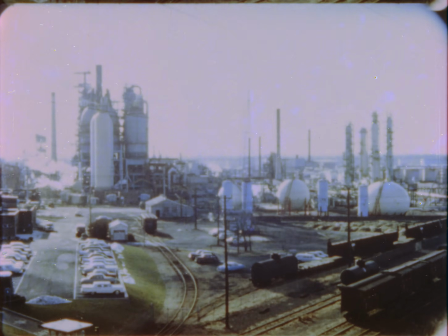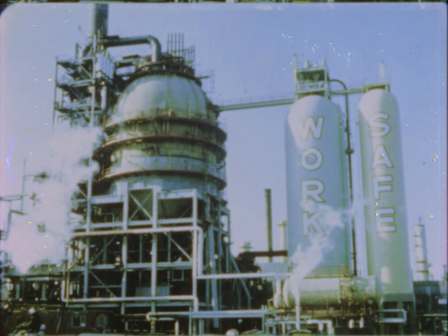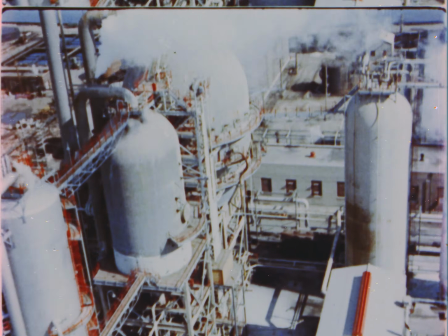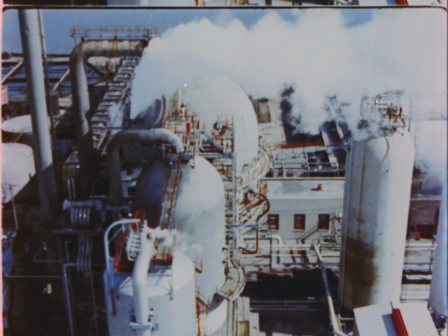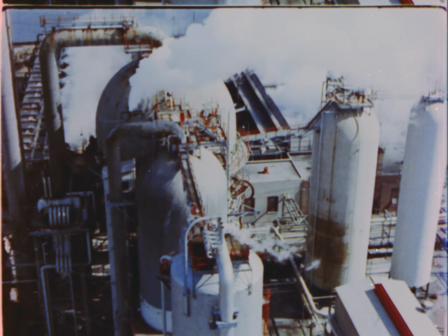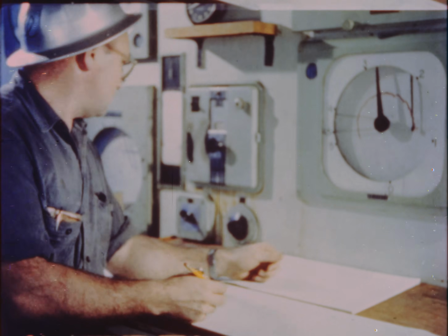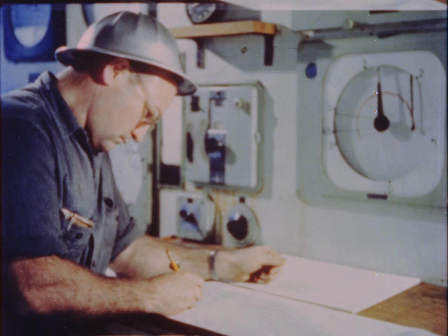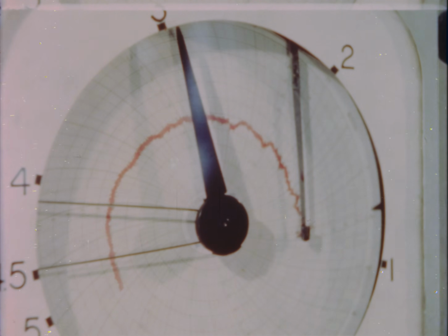At this refinery, level measurements of an entirely different scope are made with an isotope gauge. Within this thermal cracking tower, the level of hot turbulent fluid is measured by a radioisotope source in a well within the unit and a detector underneath. The fluid level is maintained at a depth of 3 or 4 feet on the basis of a gauge dial, which is accurate within a range of 4 inches.